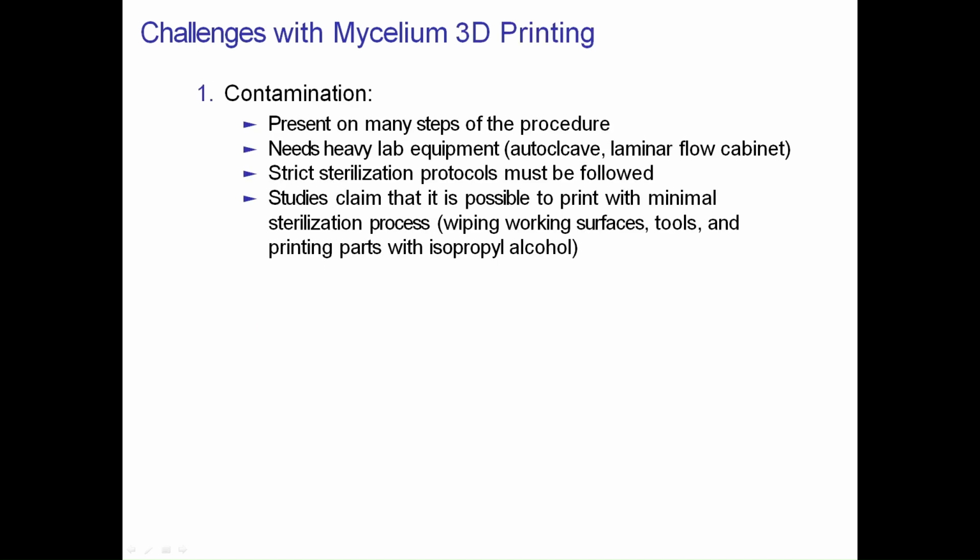However, mycelium 3D printing comes with its challenges. First and foremost, there is a high risk of contamination, making the product hazardous both mechanically and health-wise. The risk of contaminations is present in almost every part of the procedure. Studies mention that in order to avoid contamination, heavy lab equipment is needed, such as autoclaves and laminar flow cabinets, while strict sterilization protocols must be followed.